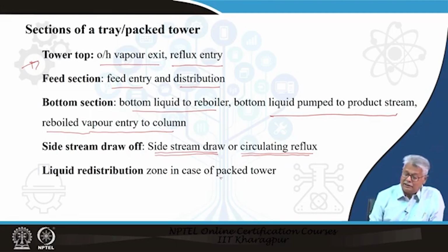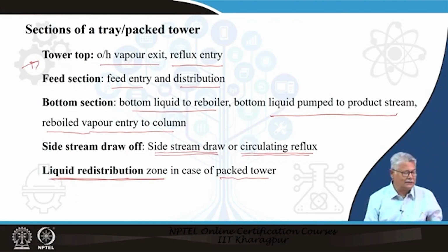In the case of packing, we have already said that liquid distribution is absolutely important. So, if you really have a packed tower which is fairly tall, to avoid any sort of channeling, you have to distribute the liquid. So, wherever you have a liquid distribution zone, how it is done, what exactly is the physical arrangement, we will have a look.